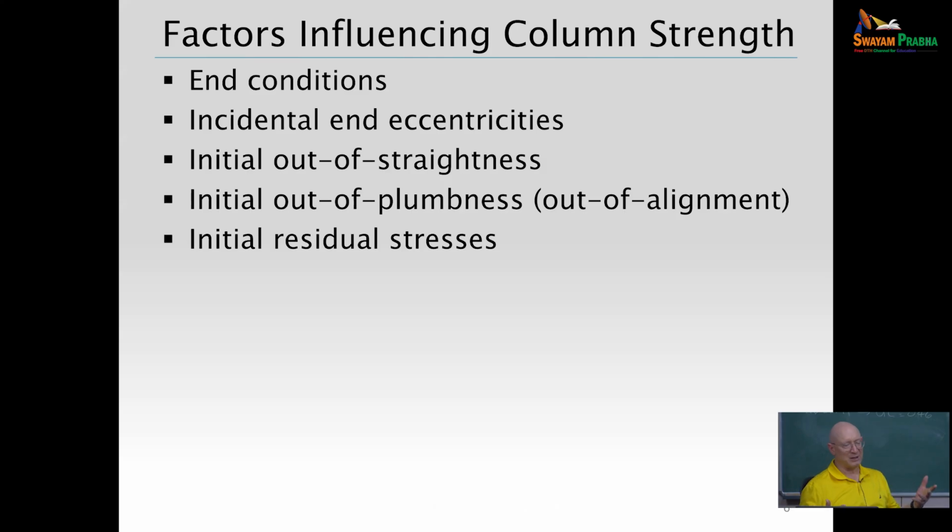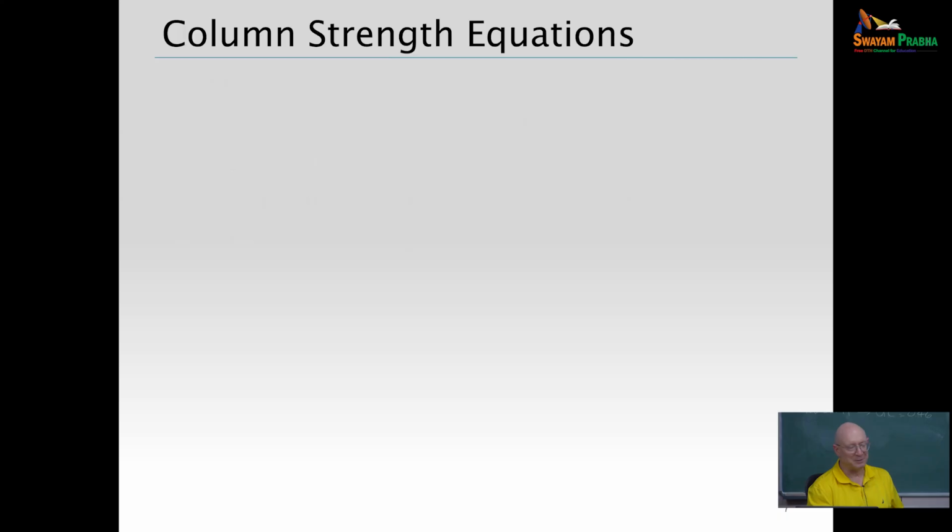Obviously, we know that your end conditions, any end restraint that you have on the columns, will influence the column strength. Any end eccentricities, out of straightness, out of plumbness, or out of alignment, your initial residual stresses, all those things are going to impact your column capacity.